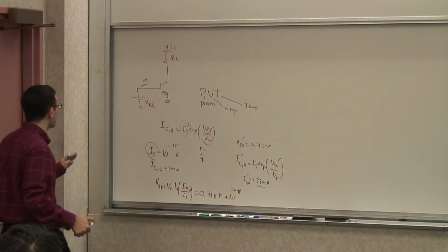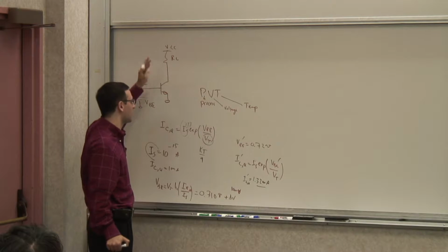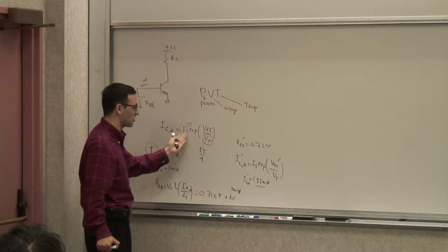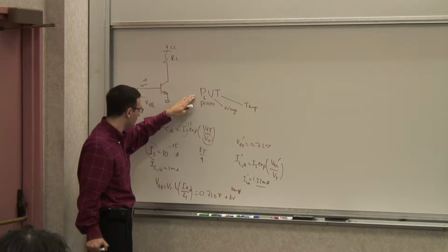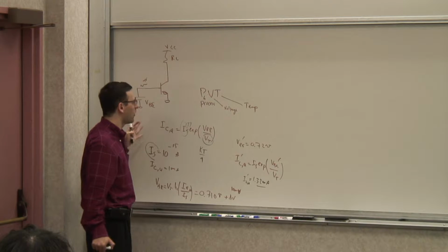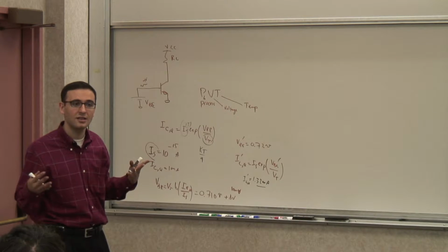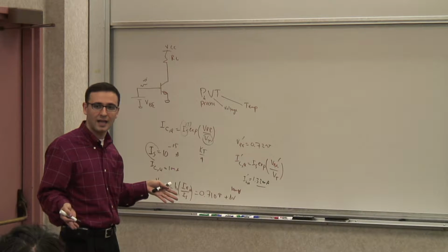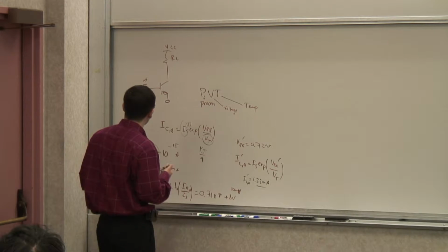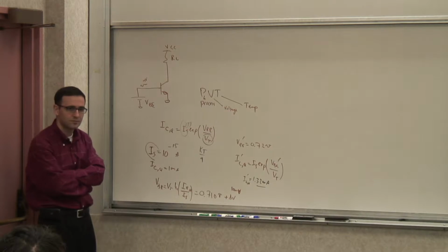I have a strong sensitive dependence on this voltage, if I use a voltage source generated off of the supply, let's say. I have a strong dependence on temperature, as we saw, and I have a strong dependence on the process variations, IS. So I'm starting with something that's horrible, and we want to see if we can make something that eventually, ideally, is independent of all of these, and is not very sensitive. So let's start with this and see what I can do to improve it.